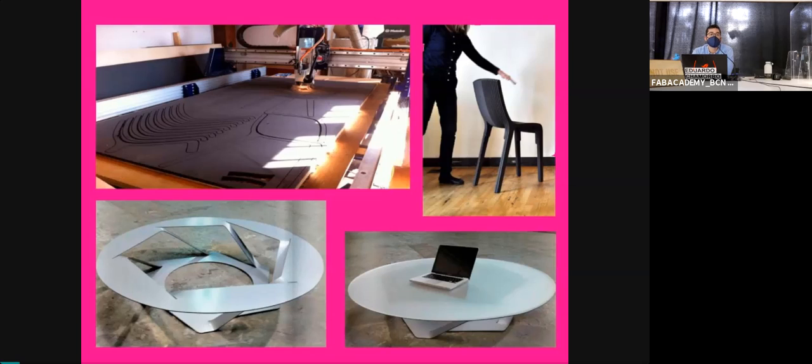In the CNC, the maximum thickness of material is not determined by the technique, it's determined by the machine. Some machines have a higher bridge that is more or less this distance, and this will determine the amount of material that you can cut. The mill bit can cut whatever size. It depends on the collisions that you have on the machine, not on the technique itself.